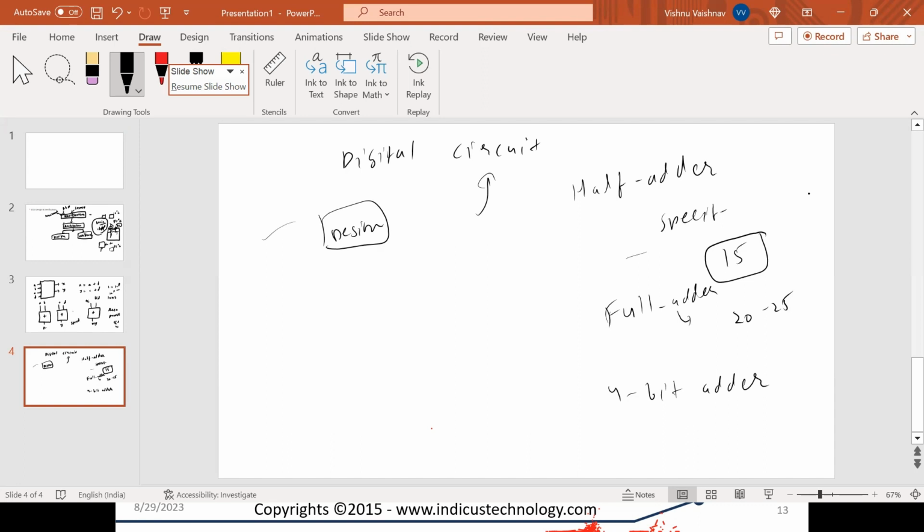Because this time it's 9 inputs, which means a 9-variable K-map, which practically we never worked with. K-map is there to provide a convenient solution so that we can easily get the circuit and the correct equation. But with 9 variables it becomes bulky. Instead of helping you, it actually disturbs you. So if you are thinking we'll go with a K-map, no, it won't work.